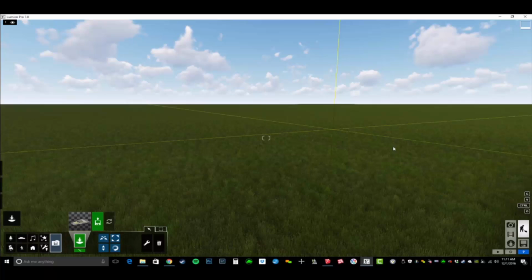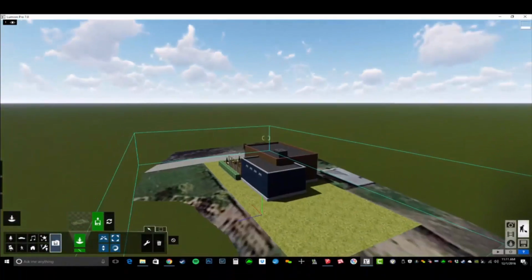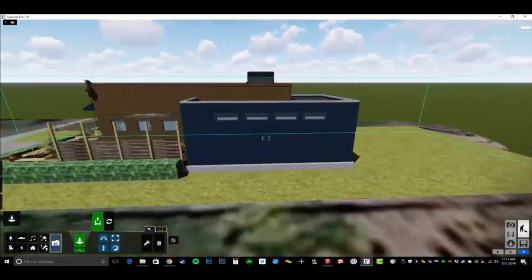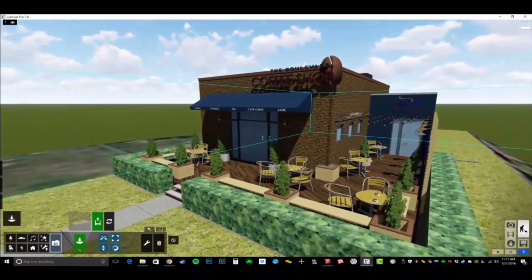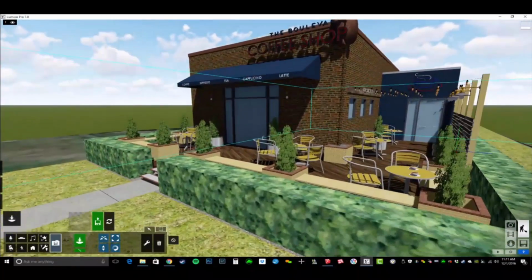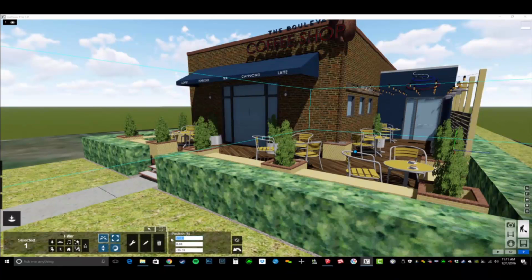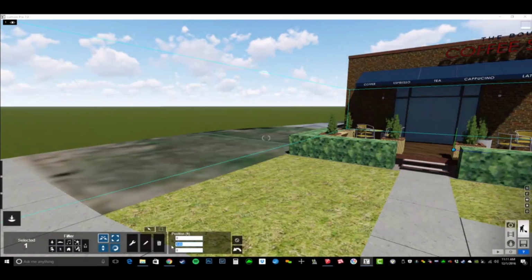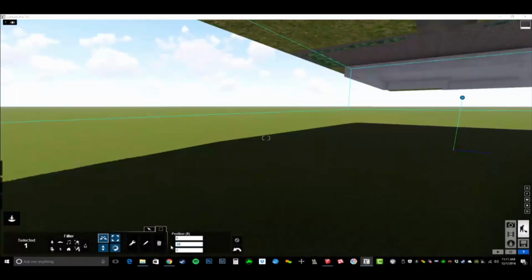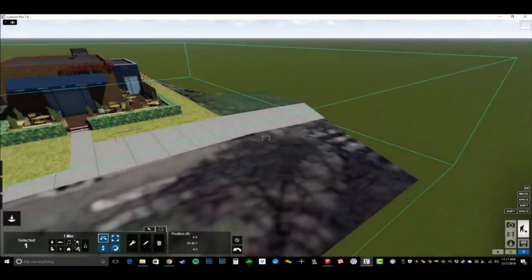Let's do that, but I'm going to click to place that model. I'll tap Escape to remove it from my place mode. All right, so here we go. We've got our new model in there, and then let me make sure that I place this model. Normally, I would place this at 0.50, but today we're going to use 16.4 just because our site is a little bit taller and has some more grade to it.